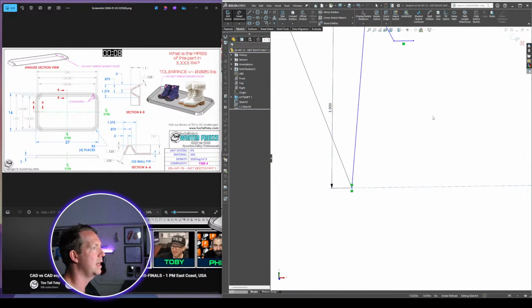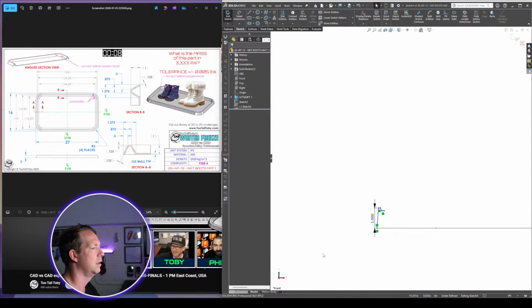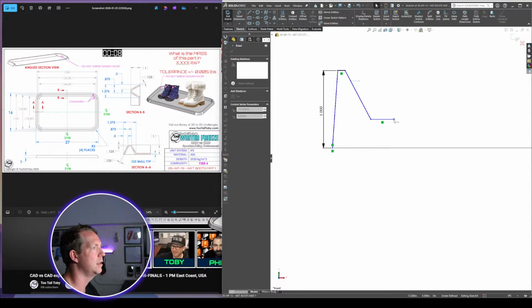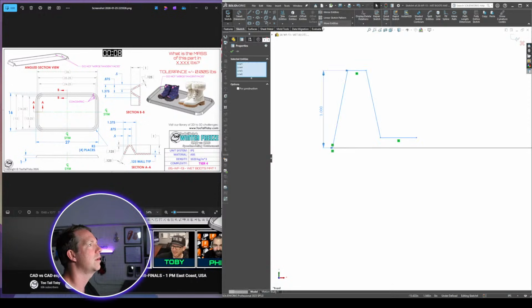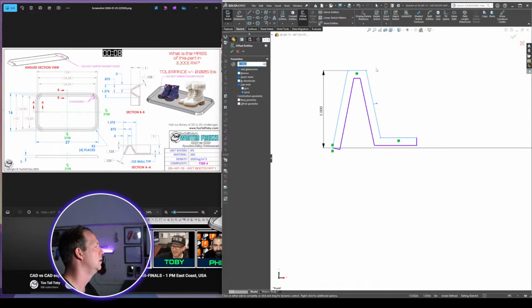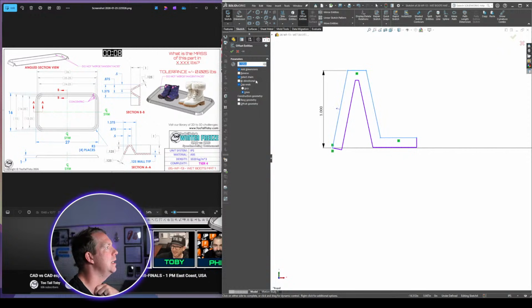Now I'm going to scale that up and just bring this back, bring this across, bring this across. All right, so I grab that, offset, 0.125, and I'm not going to cap ends, just press OK.